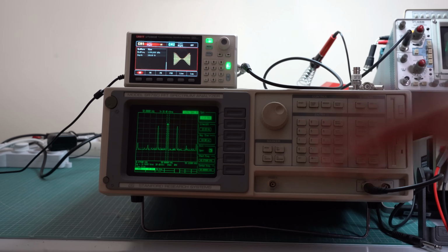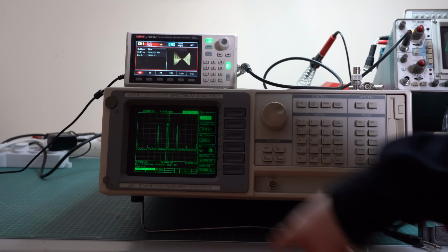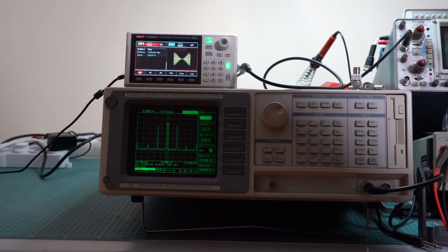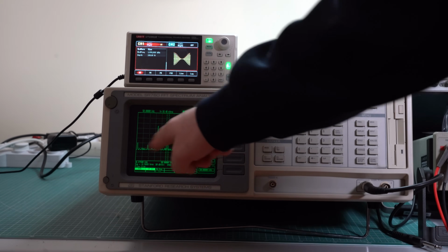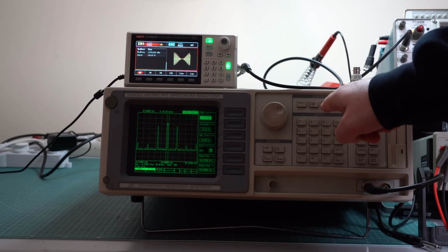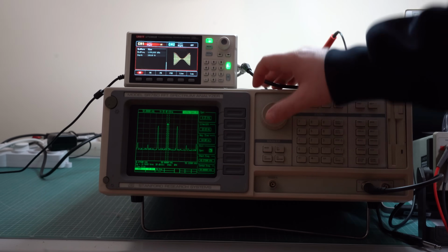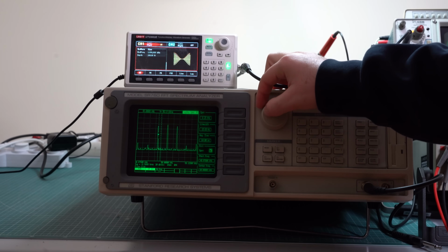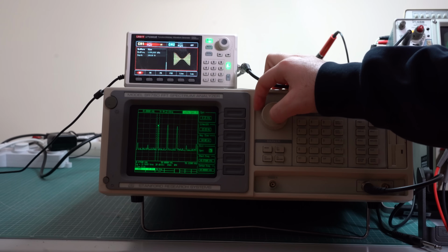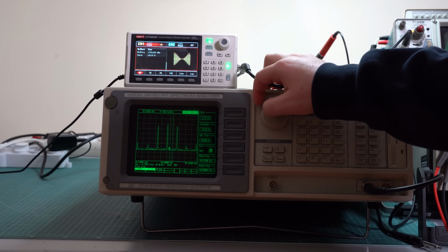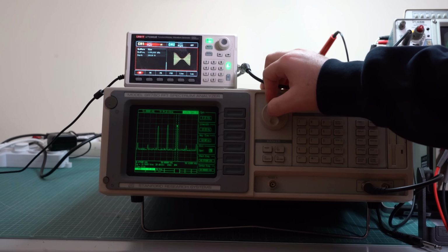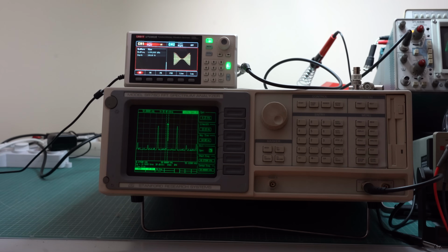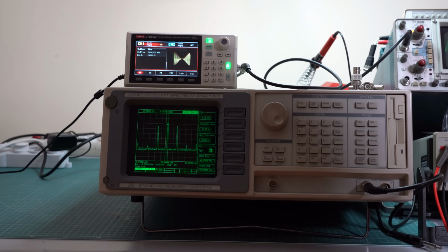As you can see, we reduced our span to just 6.25 kHz, and now you can clearly see the sideband signals. By selecting the marker, you can even measure the frequency of these sideband signals to see if they are right or not. And as you can see, they're bang on. This one is at 49 kHz and the upper sideband signal is at 51 kHz. So this is what the span can do for you.